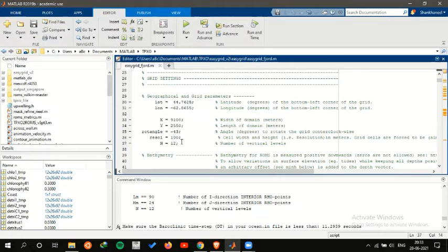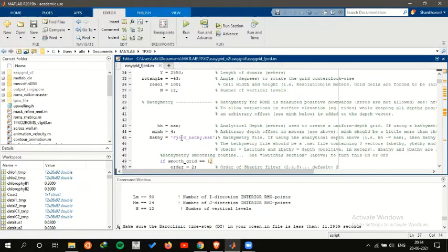Since this is a 3D grid, this is essential, as when adding forcing files, these forces will be added to different layers of our domain. Now coming to the bathymetry, we don't need analytical depth, so just keep it as none, because analytical depth will consider the entire depth as constant and will have a rather flat bottom, which is not the case. And since we are using a bathymetry file, you just need to mention the bathymetry file in the .nc format in here with the correct extension and the correct name.